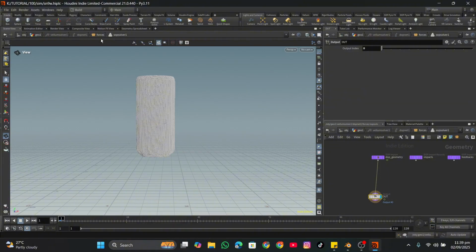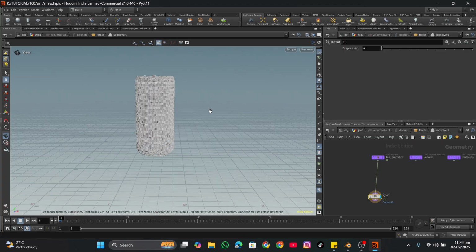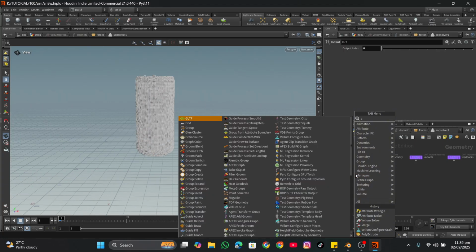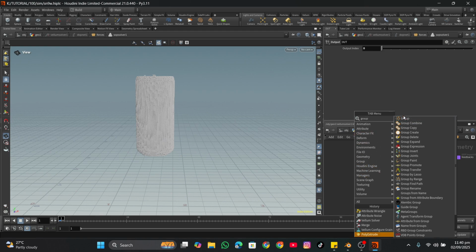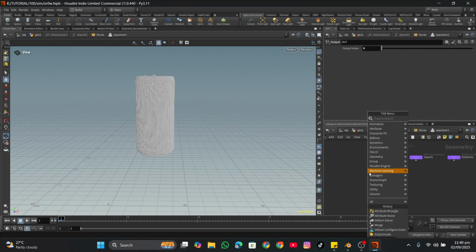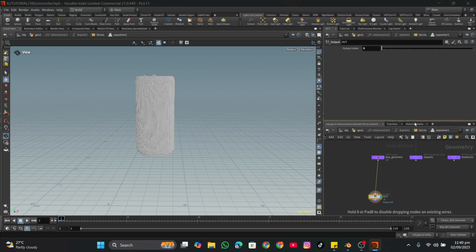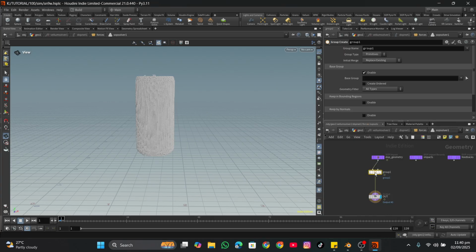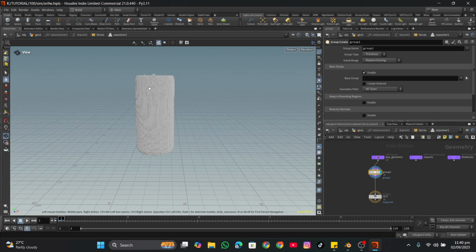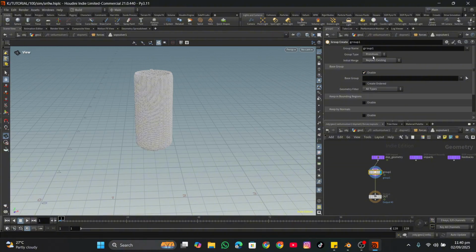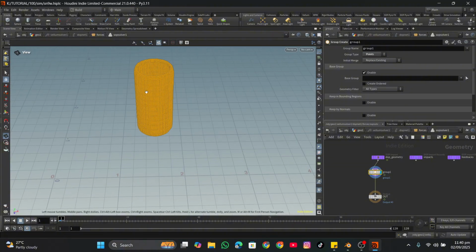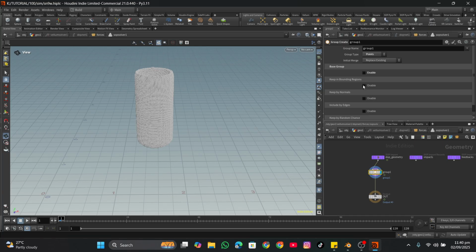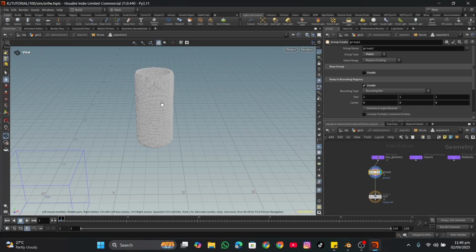First of all, I want to create a group that goes down to slowly select those particles. So for this, I'm going to create a group node, and connect it right here. If I look into it, and if I turn these into points, now all the points are selected, but I'm going to turn these off. I'm going to click the boundary one. I'm going to click enable.